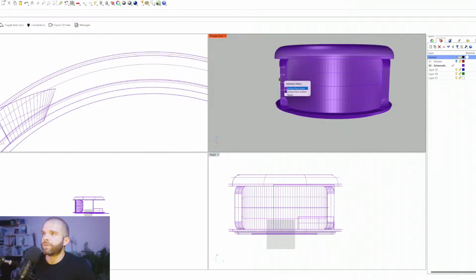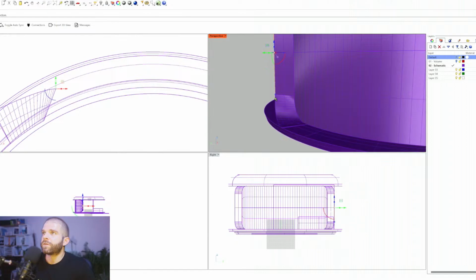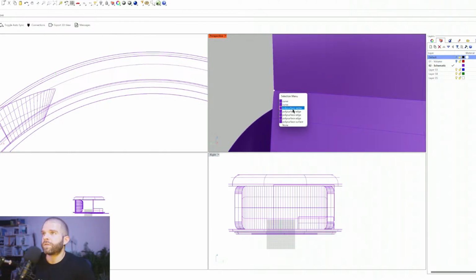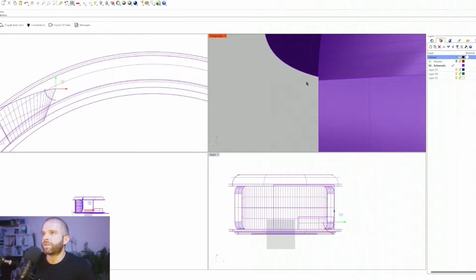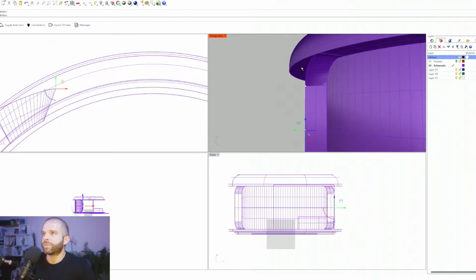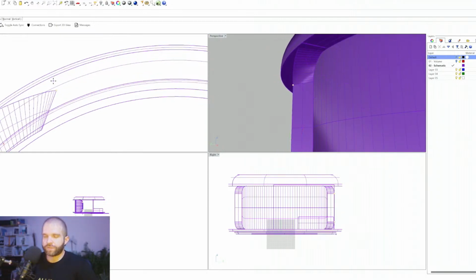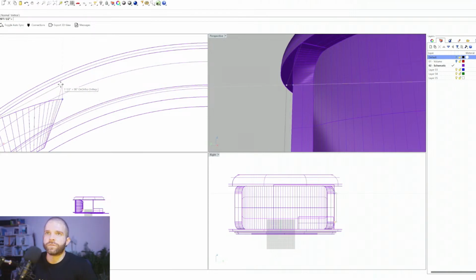Okay, come on now. Even better. Let's select the point, vertex. If I move this point, everything moves with it. So let's select that vertex there and this one here. And I need that to match the edge of the circle. So can we, yes, if I hold shift, I can lock it into that axis and then just snap to the outside of the cylinder.